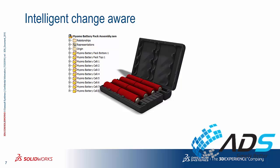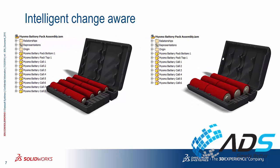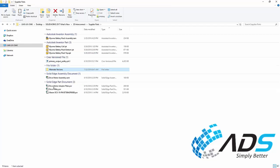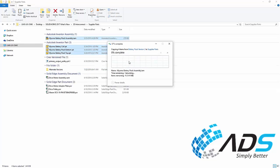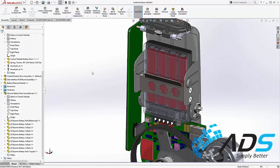Within Autodesk Inventor, we've made several changes to both the parts and the assemblies. You can see that not only are the batteries longer and much bigger in diameter, the housing has also changed. It also now only includes 6 batteries and a much more rounded housing to contain their larger size. To simulate the change without Autodesk Inventor, we're simply going to overwrite the existing files with a new version we have on hand. When we go back to SOLIDWORKS and perform a rebuild, you'll notice there's now a small refresh icon on the assembly, letting us know that it's seen a change in the native CAD files.